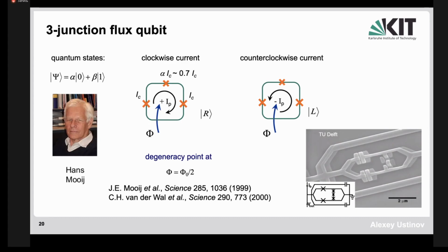So instead of having now, this is our quantum junction, instead of having now a junction in superconducting loop with particular geometrical inductance, he suggested to make a very small, a very tiny inductance, and to add the inductance to the loop needed value. He suggested to have here two Josephson junctions, which will have critical current larger than the quantum junction. Typically, a quantum junction will have about 70% of the current of the large junctions. And this was really kind of breakthrough.